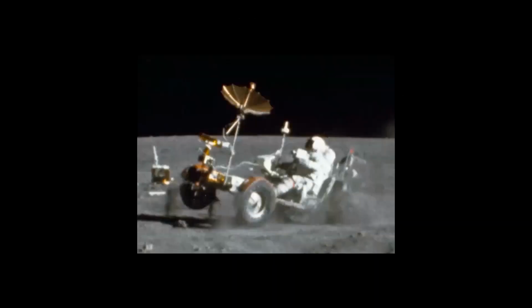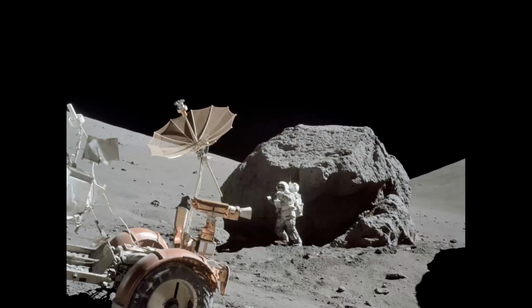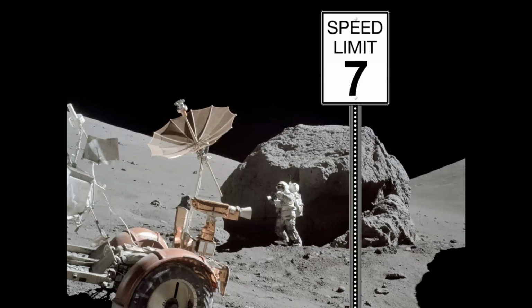The primary limitations on the trafficability of the lunar soil are speed and slope climbing. The normal cruise speed of the Apollo lunar roving vehicle was 6 or 7 kilometers per hour. This speed was constrained by the irregularity of the cratered surface, coupled with the low lunar gravity. But the speed of a future lunar vehicle could be increased by modifying its dynamic response. In other words, by using larger diameter wheels, or an increased wheelbase, or a greater mass, or a softer suspension system. Or we could always just build permanent hard roads on the moon.